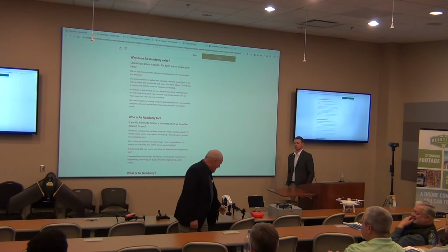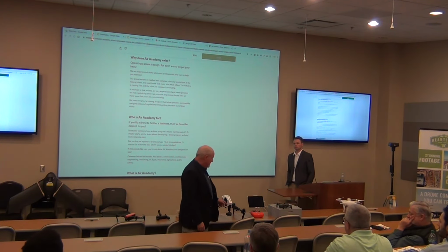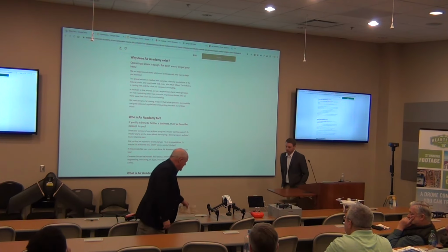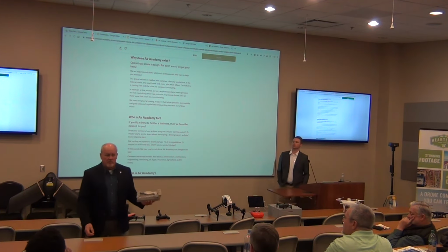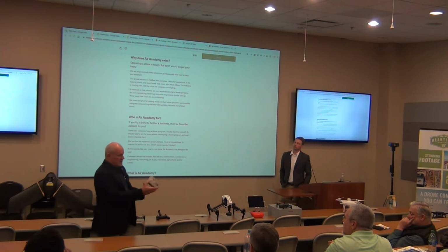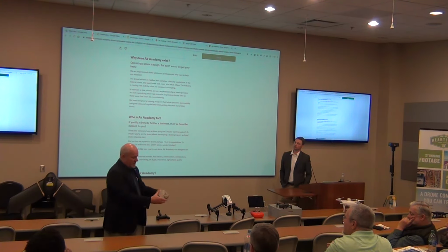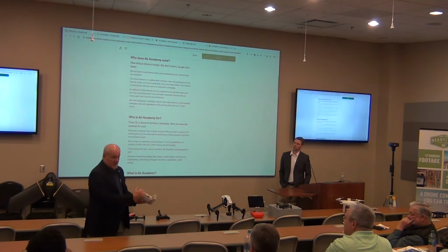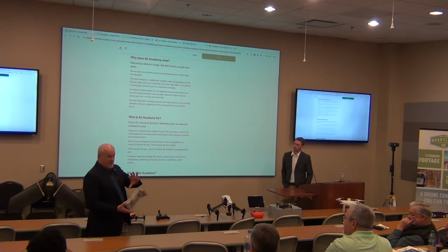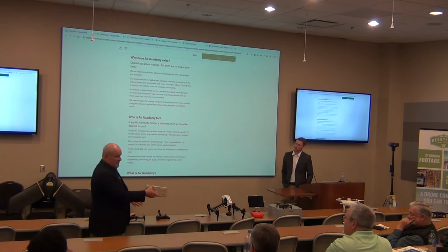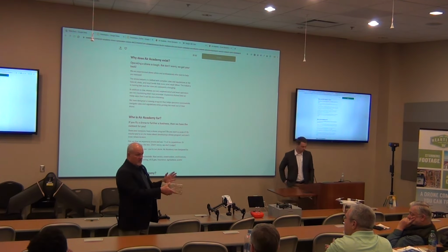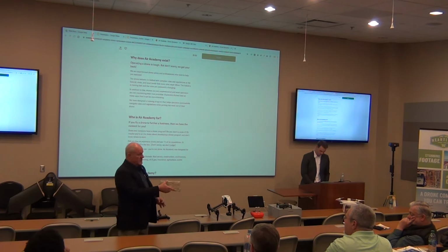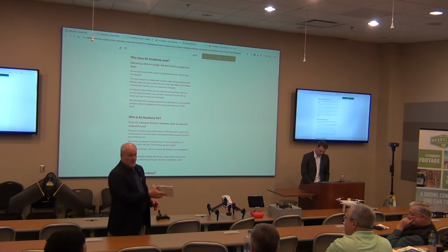And then this is the FLIR camera, the XT on the Inspire, and we were able to detect an installation problem, an installation complication. This is a man-made stone veneer. I call it peel and stick. The contractor used a money and time-saving method of creating a donut application of the glue, basically the mortar, when it should have been fully back buttered according to the specifications. So 25,000 square feet of man-made stone veneer on a mixed-use commercial building, residential, scholastic, and a grocery store, and these 10-pound stones are falling off the wall.